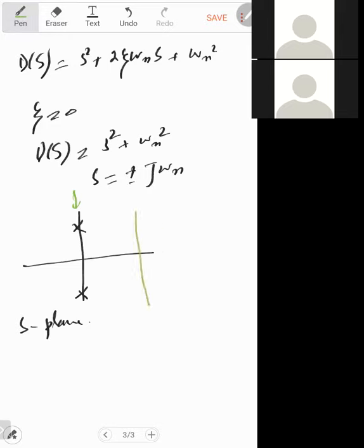If we find the response, the response will be like this. See, it is marginally stable because it is giving you the bounded output, but it is oscillating, so it is not coming to a single steady state position. So we also call it the undamped case. Undamped, okay, you see there the amplitude is not reducing, so it is called the undamped case.